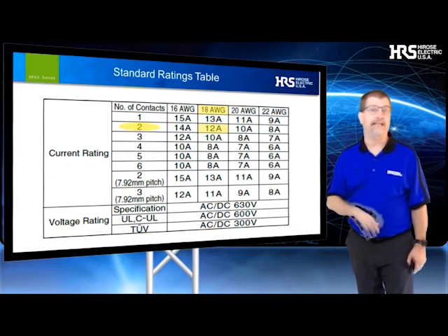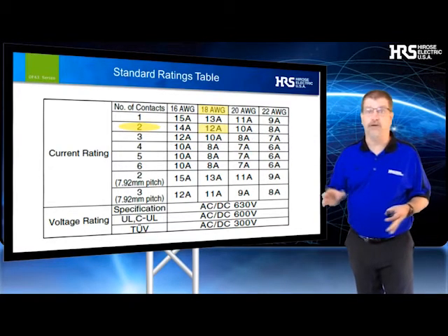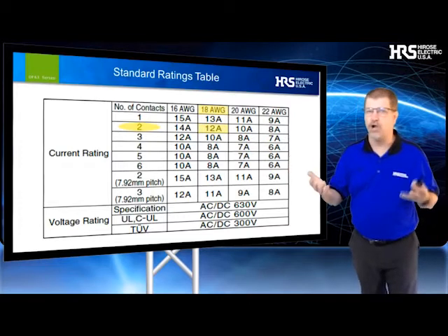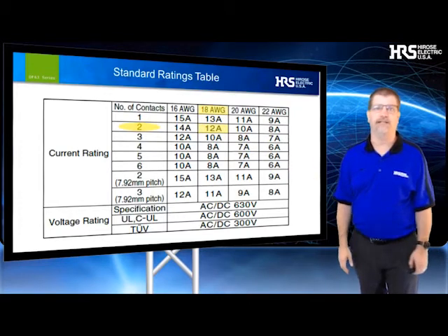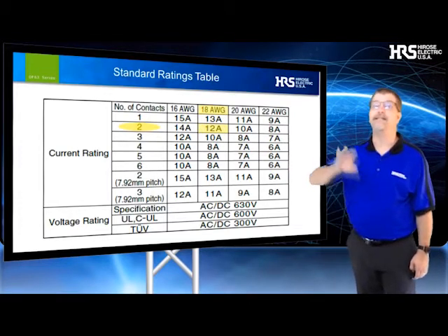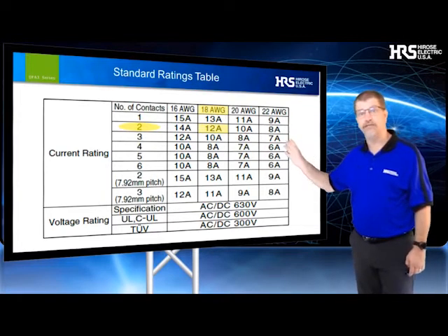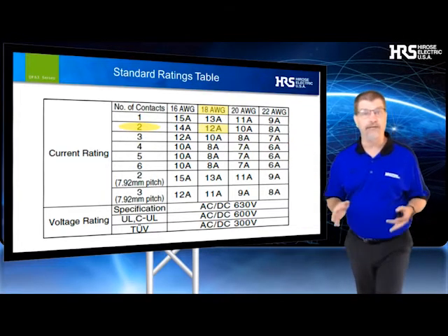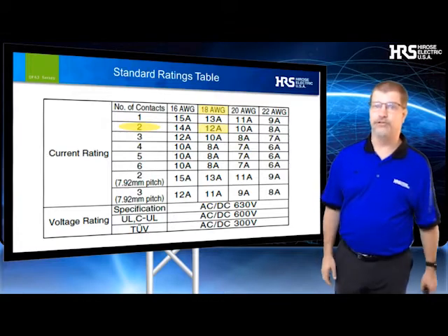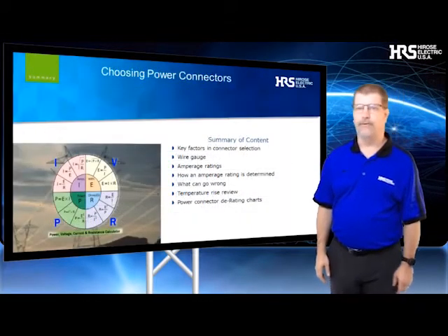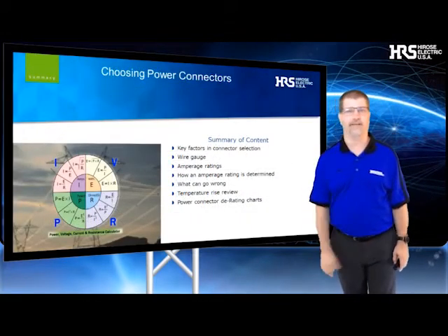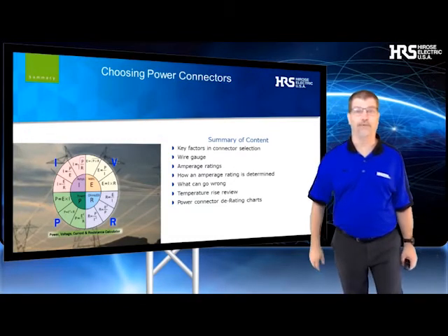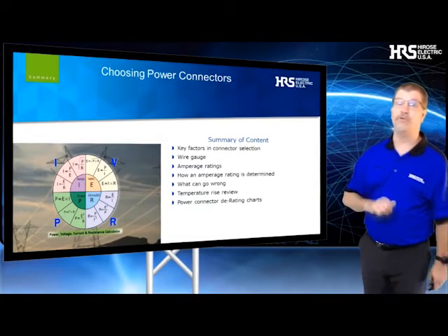If you're in a situation where you're splitting a single higher current, maybe in a smaller connector, over multiple contacts, that's when we need to consider additional derating beyond what you see in this chart. And that value could be up to 1/3 the original contact rating. Wow, we've spent a ton of time on the amperage rating, and rightfully so. It is probably the area I get the most questions on.